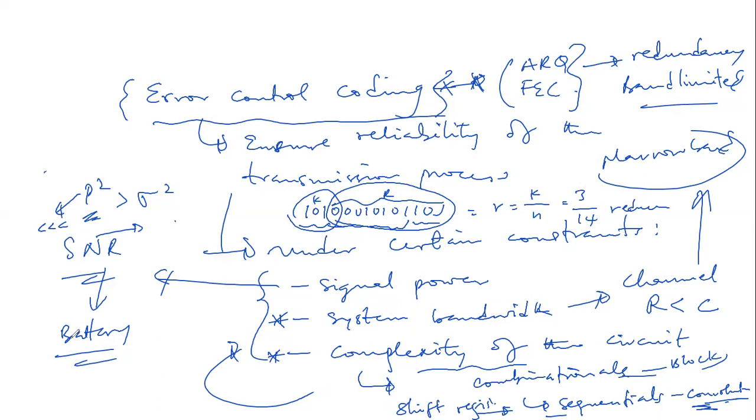So introducing redundancy into the message bit, so as to correct for errors or to make it more robust or resilient against channel effects or errors, actually lowers the data transmission rate. Alternatively, if it's uncoded, then we increase the channel bandwidth.